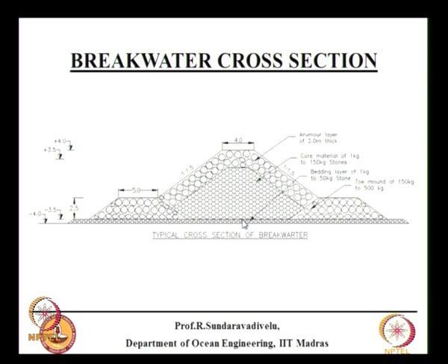Any doubts in this? One of the major designs we have now done, if we take a typical port today, it is being developed for about 10 million tons, because the viability will not be there if you do it for a greenfield port of less than 10 million tons. To develop a port to handle 1 million tons, it will cost 100 crores. This is some block cost estimates. So for 10 million tons it will be 1000 crores.